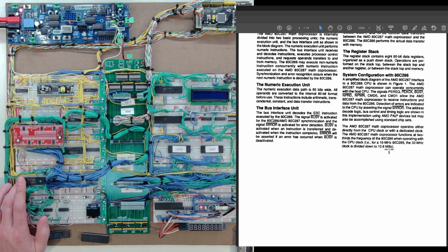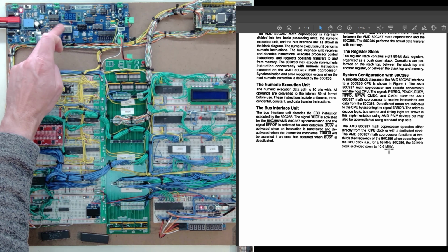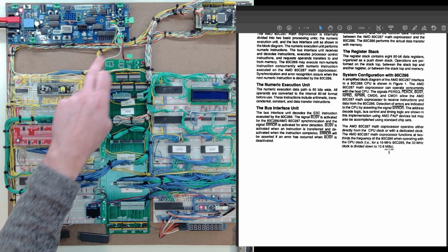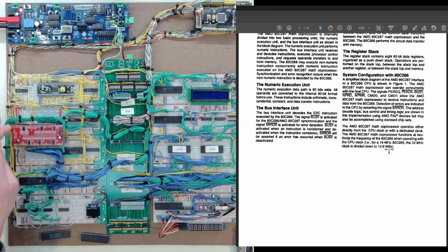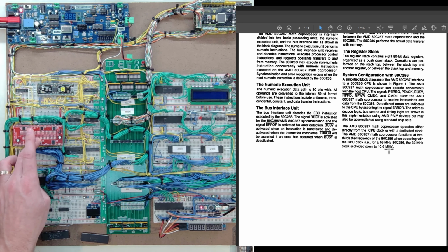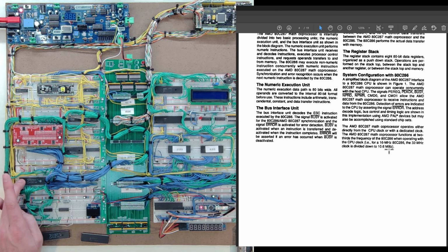Well, either way, if I do the math on mine, I'm running a 24 megahertz going through a flip-flop. So coming into the system is 12 megahertz. Processor's running, therefore, at 6. And whether I take 2/3 of 6 or 1/3 of 6, that's still well below the rating of this 10 chip.